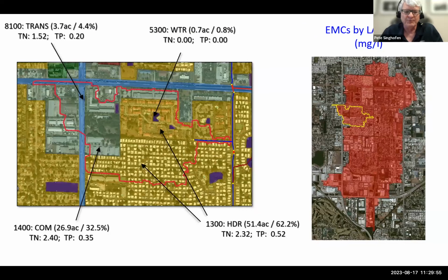So here's an example of a catchment area basin that has multiple land use types within it, so the hydrology is distributed. We have tools in ICPR where we can intersect a basin or catchment map layer with soils and with land use to form subpolygons.